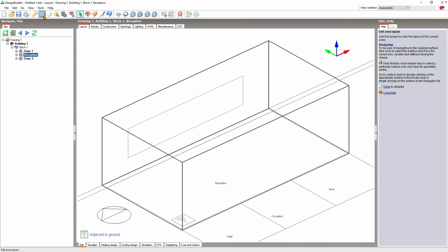This is explained in a later tutorial and the program help. If you have significant thermal mass from concrete or masonry objects in your zone, you can model the thermal capacitance of that by drawing a standard partition that does not fully enclose a space. You can find out more about that by using the search term hanging a partition in the program help. This finishes our quick review of zones and partitions in Designbuilder.